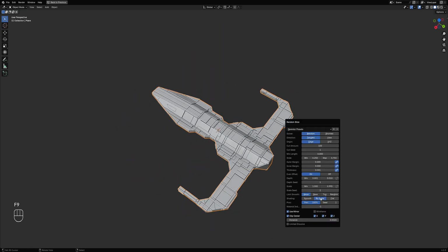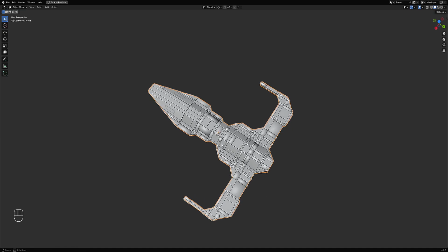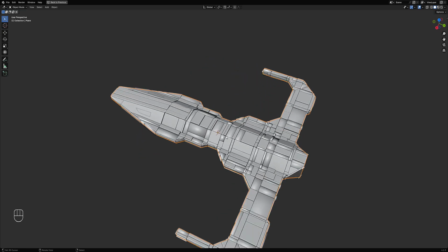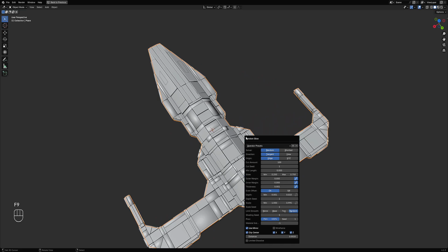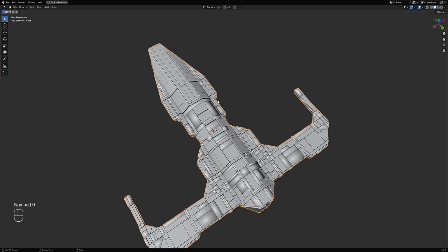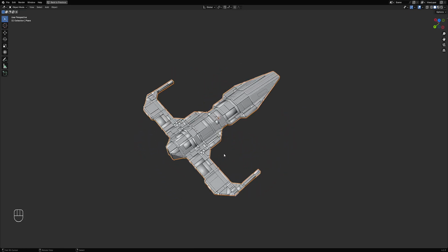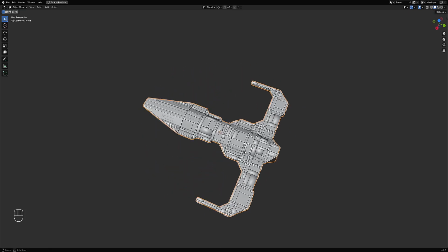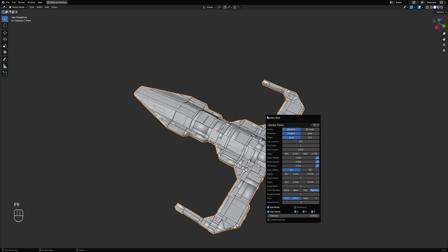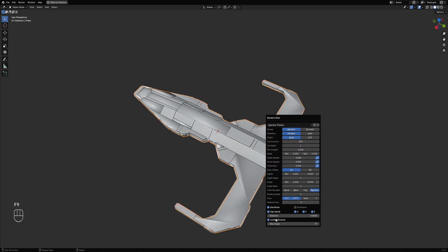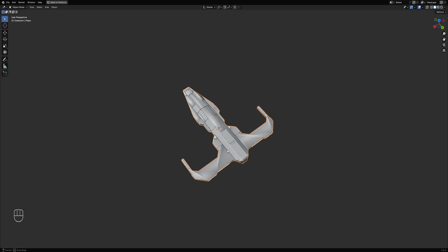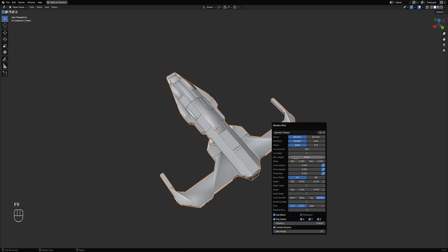Okay, let's try randomizing. So the cuts are made per face. So in order to create large faces with larger areas, you can just limit dissolve the source mesh. The limit dissolve will only affect the proxy mesh created by the script and not the source mesh. So in object mode, this process is non-destructive.